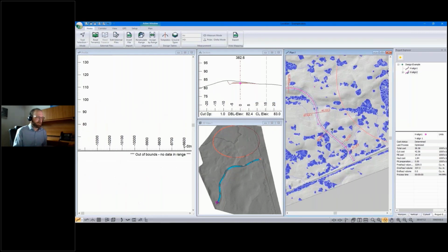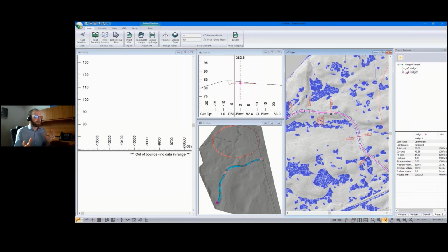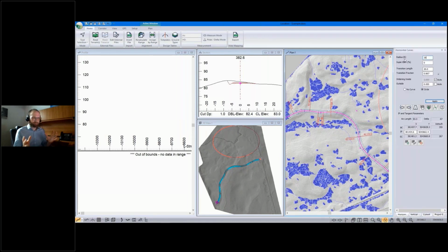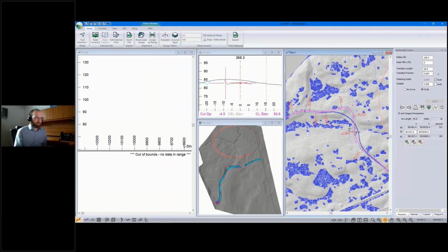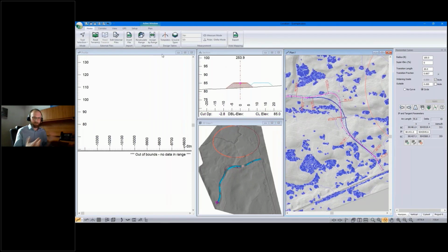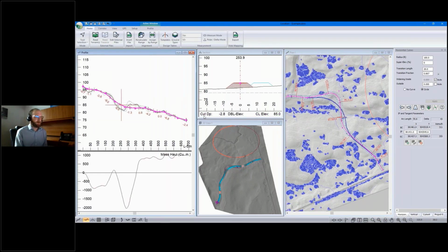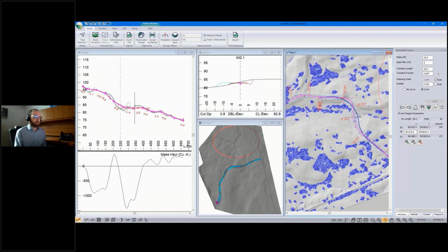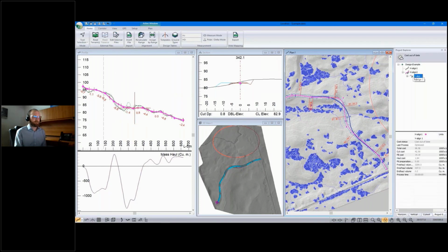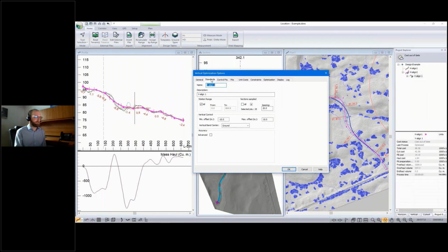So I've duplicated my alignment and I can make adjustments. And in this case, I'll go a little different direction with it. So instead of trying in a whole new option, well, maybe from a planning purpose, it's valuable to know, do we want to weigh the economics of having a fast road and having reduced cycle time for what we're hauling out of there, or do we have a slow road that's going to cost us less to build, and probably a smaller environmental impact? So I'm changing some curves to be a 30-kilometer-an-hour design standard, and I'll change my optimization to be a 30-kilometer-an-hour design standard.